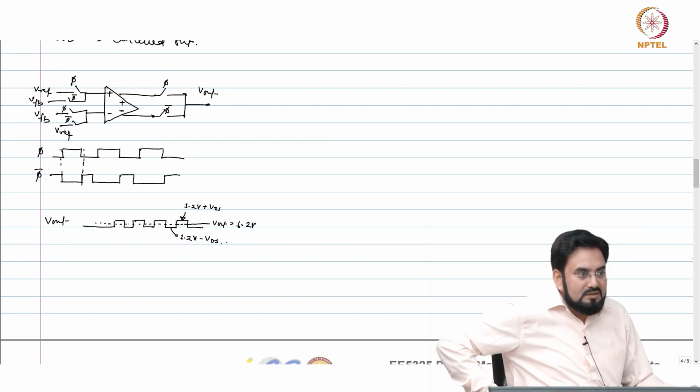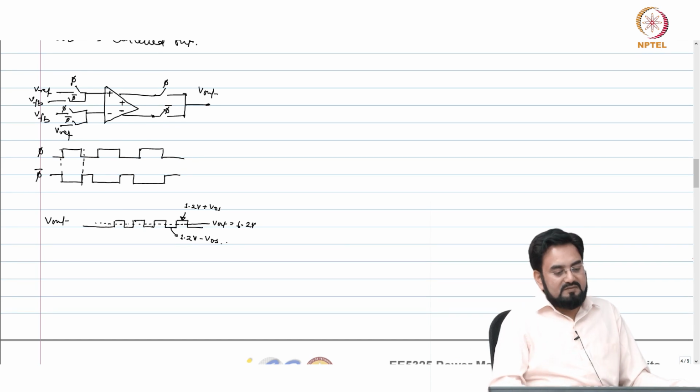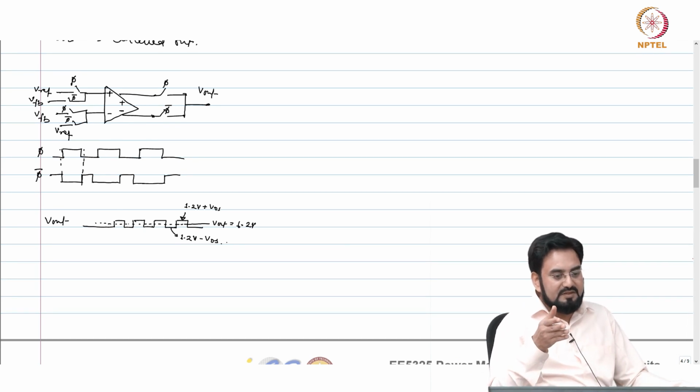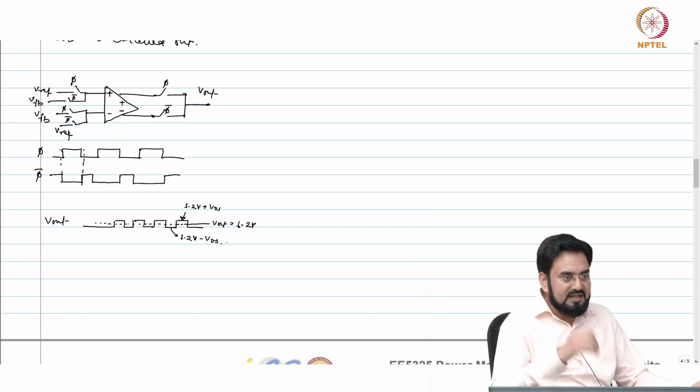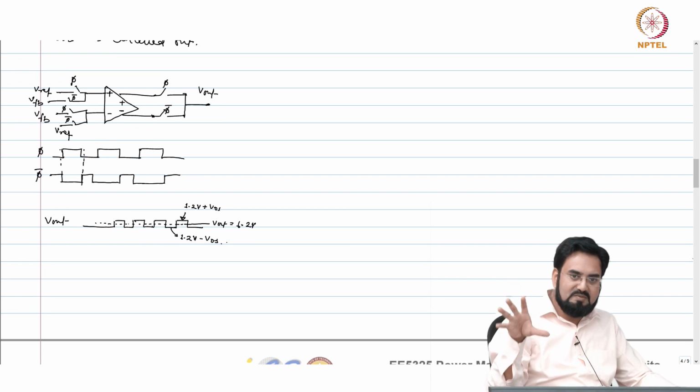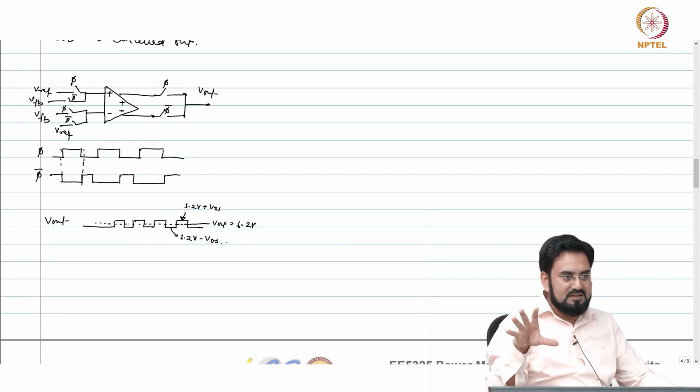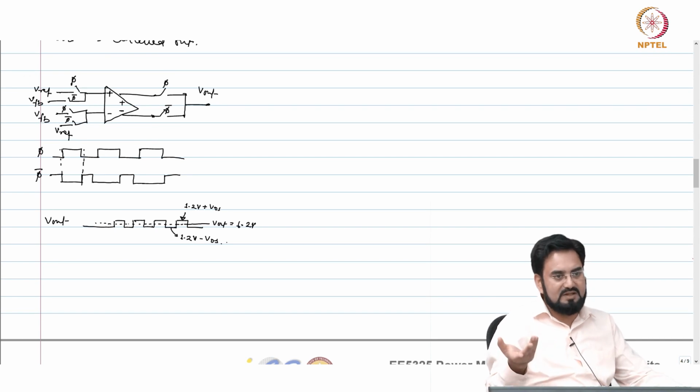Using static, we are reducing the offset. With the static, so if I want to reduce, let's say with the static I want to reduce by 100 times, then I know it will require a very high resolution DAC or all those resistors, which will make it very complicated. So what you do, you just use a 3 or 4 bit resolution there. So you know that your maximum offset can be 10 millivolt. With 3 to 4 bit you can bring it down to, or with the 4 bit bring it down to less than 1 millivolt. Okay.